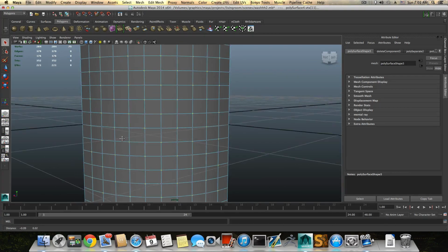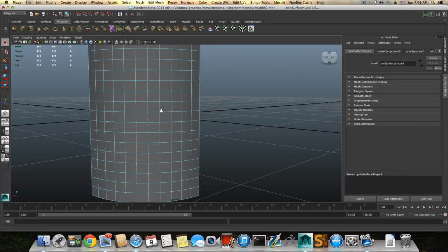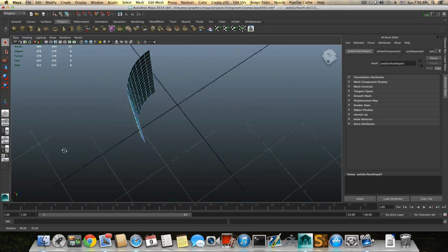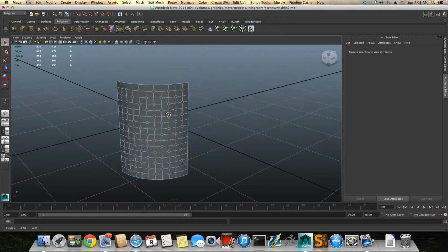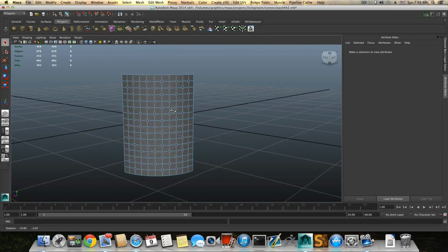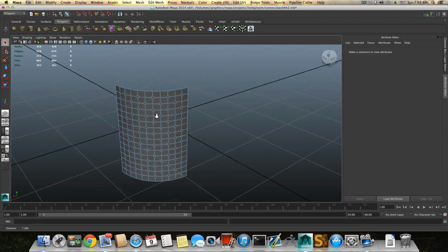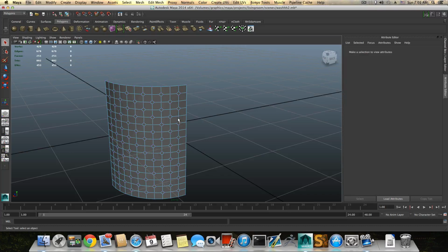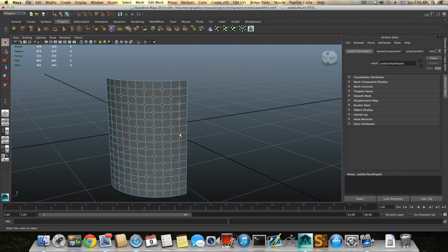Let's see. Okay, so while all of those are selected, see how it looks. Hold the shift, right click, Chamfer Vertex, and this is what you will get. So you see this is how it looks. Let me just examine this. It looks okay. I want you to right click, choose face, and pick all of those. Okay, just select them, all those little squares there.